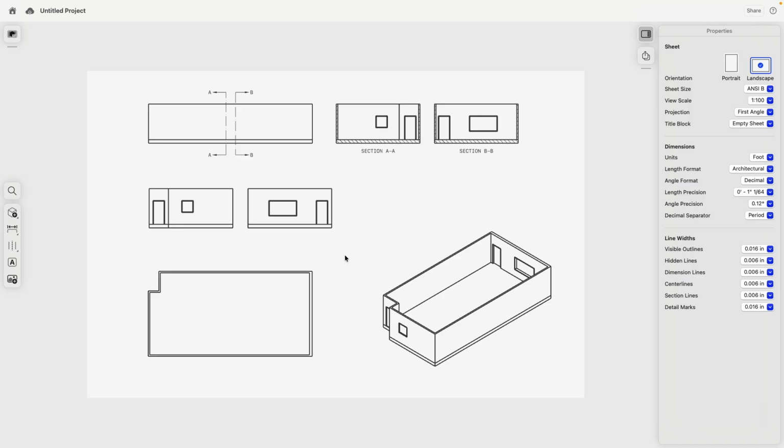Now, for presentation purpose, when we put this into a project page or so, we also want to have some basic dimensions, which we could add manually, or we can do this directly here. Here is a wall. I select it, click done. There's a dimension. There's a dimension done. And you see when I move them, they also snap in certain increments, which is quite nice. There is an edge. Beautiful. I can move this out. And for example, here, bring this over.